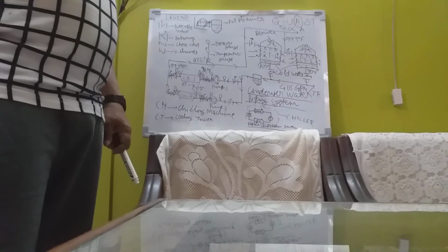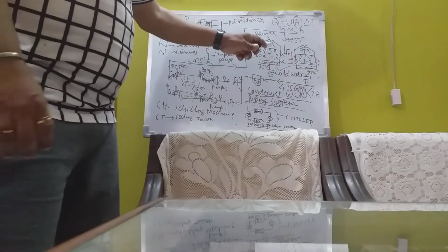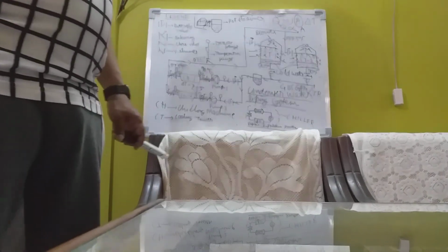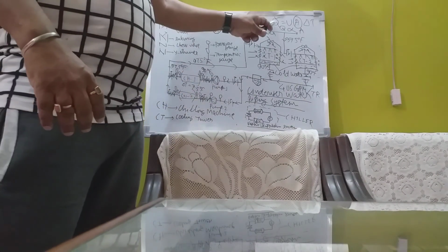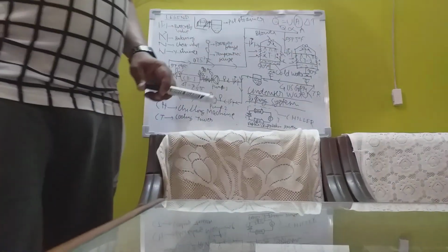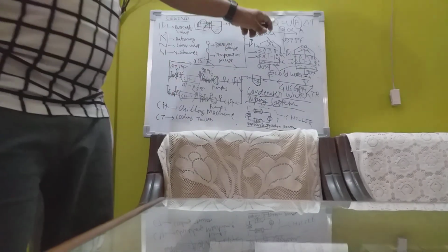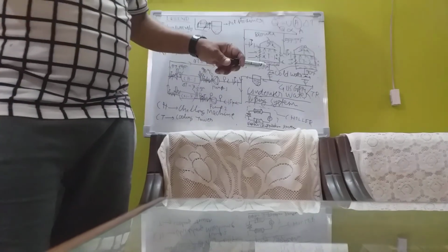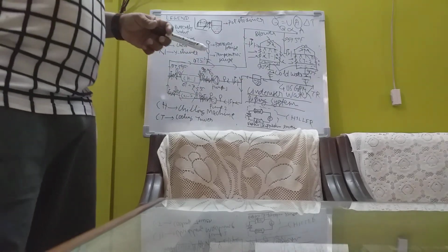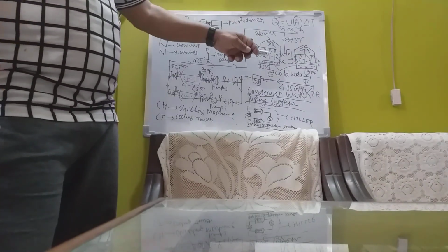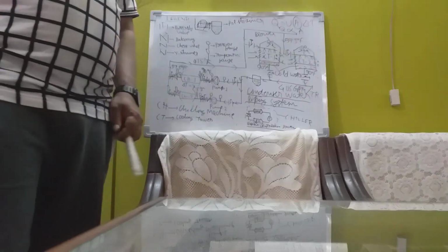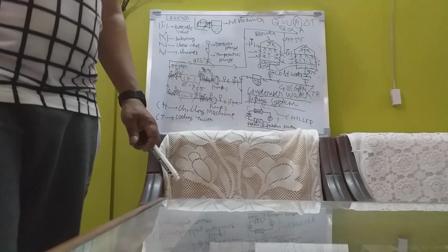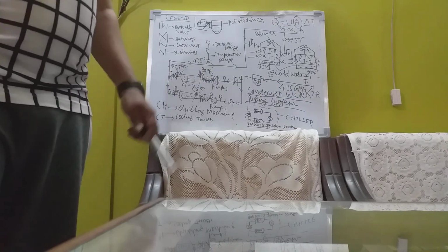Important point you have to remember. Here, in case of the cooling tower, the surface area increases. You know Q is equal to UA delta T. You have already read in heat transfer. Q, the heat transfer, is directly proportional to area. The more the surface area increases, the more is the heat transfer. Taking that into consideration, I have sprinkled this water into small droplets so that the surface area increases tremendously. And because of this increase of surface area, the heat transfer increases. And as the heat transfer increases, the water gets cooled and is supplied again and again. This is how the whole